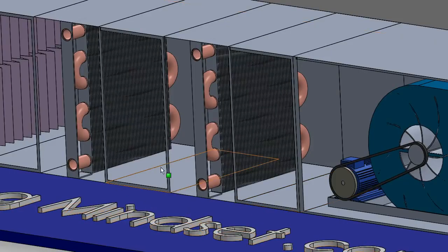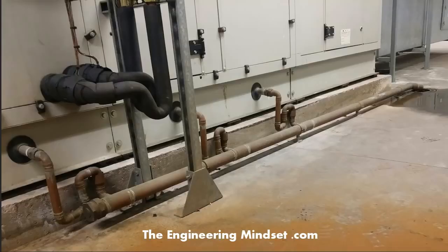Now underneath the coils you're probably going to find that there is a drain and some drain lines coming out. I haven't drawn it on this example here, but I will show you what they look like in the real world. So they're going to look a bit like this, with the drains coming out. You go into a U-bend there to stop the flow coming back, and that just comes down this pipe, which is on an incline, and heads down to the drain. Looks like this one hasn't been installed too well, as most of it is going over the floor rather than down the drain, but it was a good attempt, I guess.